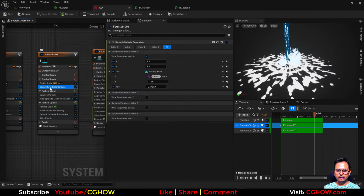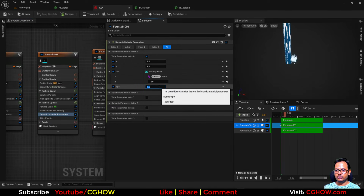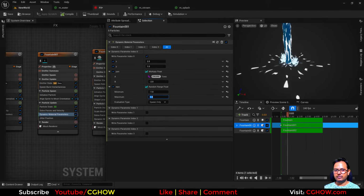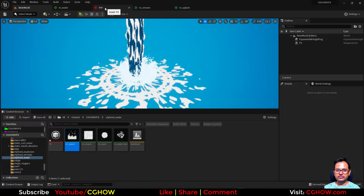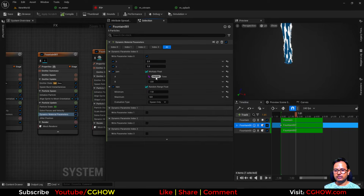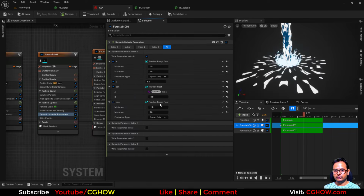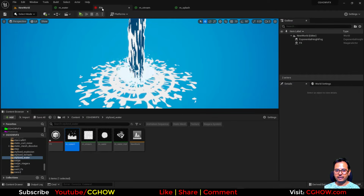So what you can do, you can spawn like 5 particles and you can randomize this from -1 to maybe 5. Now you have something like water. And that noise texture, you can randomize this also. So the tiling, this is 2. I can use 1.5 to 2.5. And here you can use 0.8 to 1.2. So every particle will have different.